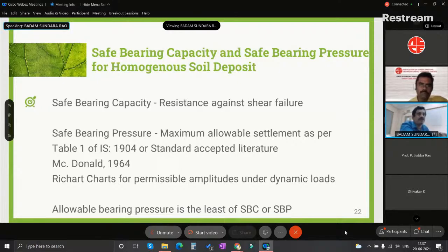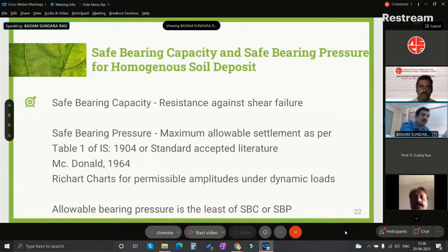These two are important. The total settlements will not have any detrimental effects on the structural system. That is the system reactions. We have generally considered the shear forces, bending moments, and axial forces in the columns. Then the shear force and bending moments will be affected by any settlement in the support system. The settlement will be reflected in the settlement of the columns and the beams. For any delta of settlement, we have an additional moment of 6EI delta by L square, and 12EI delta by L cube. That is the additional shear force that is generated with the delta settlement of the corresponding support.